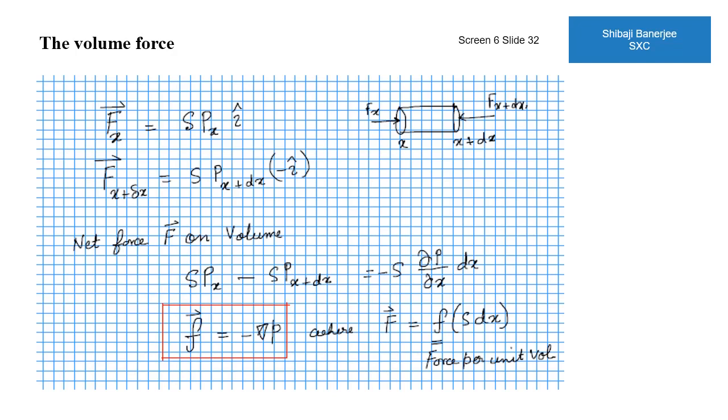The net force acts along the negative x direction and its magnitude is calculated by considering the difference between the two faces. We now consider a situation in which pressure differences can be there along all three coordinate directions. Think of the volume element to be cubical, the shape does not really matter. It is clear that the expression for net force will gather two more terms in the pressure derivatives. This leads to the final result.